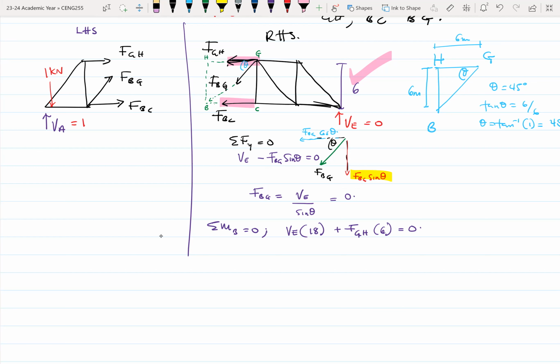Let me see if there's any question anyway. No, we don't assume. The idea of the influence line diagram is that there's always a unit load active. Sorry, I'm answering somebody's question. They want to know if we should always assume that the load on the truss is a unit load and also that the distances on the deck are the same. Because you are drawing an influence line diagram, you always draw it with a unit load. So that part is fine.